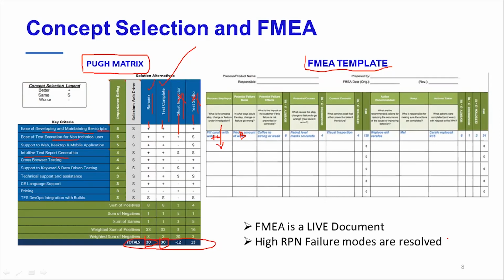There are a few components available to absorb that fuel vapor, but let's say there's nothing available, so you have fuel vapor. Now the moment the pressure of the vapor starts increasing, at a certain stage the fuel tank may burst. I'm just telling you one hypothetical situation. That doesn't happen because you have something to control and absorb those vapors. So the potential failure mode here is burst.